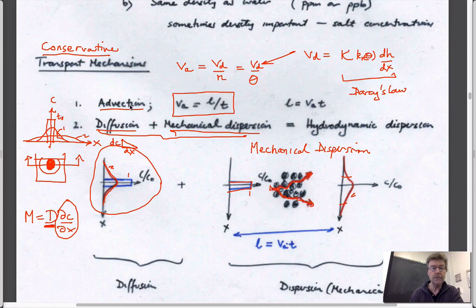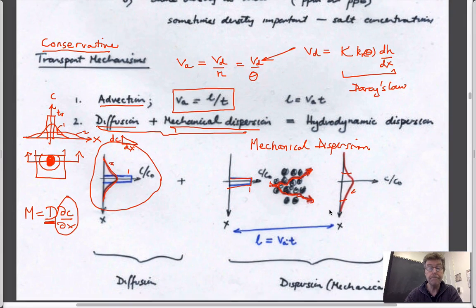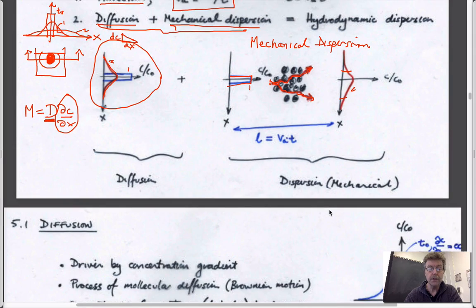So to recap, two mechanisms. Being carried downstream without any mixing is advection. But if we look at the effects, we get mixing due to two processes: one is due to molecular diffusion, which gets rid of these gradients by just Brownian motion, and also by physical mixing as it gets agitated as it goes downstream. And all we're doing is we're taking a section at two locations and being able to link those together. Okay? So that's, I think, an important concept in this.